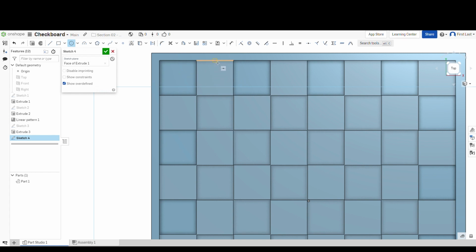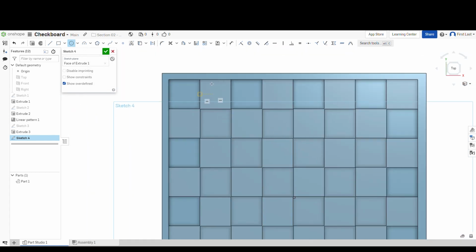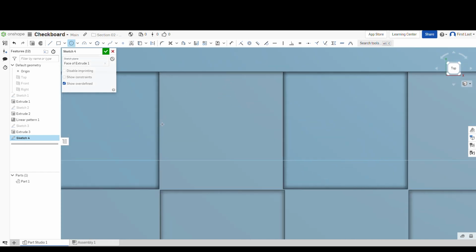If you hover over the square, you can see that we can choose the center of our top line and the center of our left line. Once you see that orange square for the center of the lines, just slowly drag in to the middle, and you can see that it shows us that we are choosing to put the center of our circle at the center of this square. Click, drag, and let's go ahead and make our checker 8 inches in diameter.